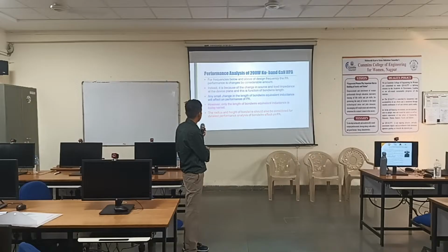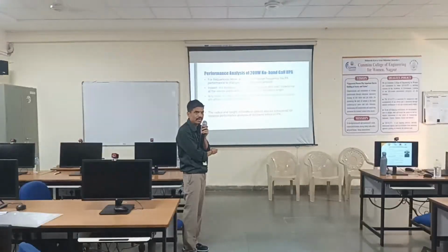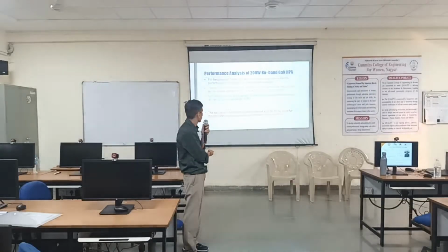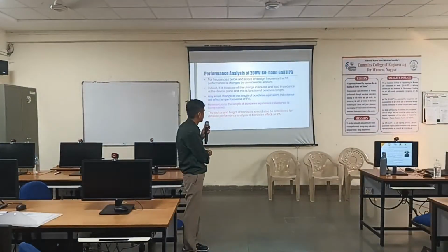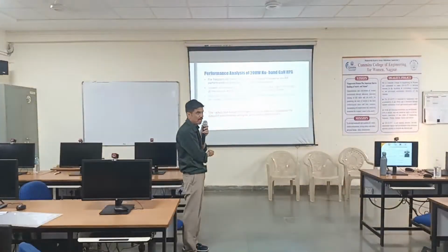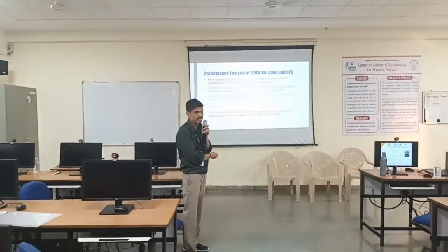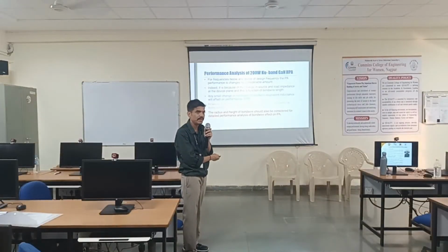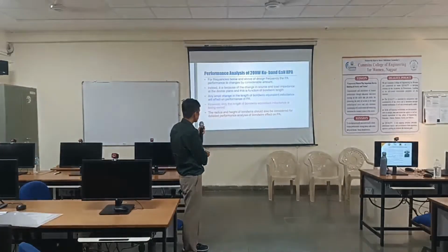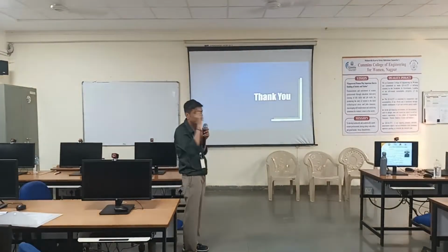Mainly on this, any small change in the length of the bond wire, the equivalent inductance will change and it will affect the entire PA performance. We only considered the length of the bond wire. However, the radius we have not considered, that radius and height we have not considered. But these can be the other two parameters which will affect the equivalent inductance and change the PA performance.